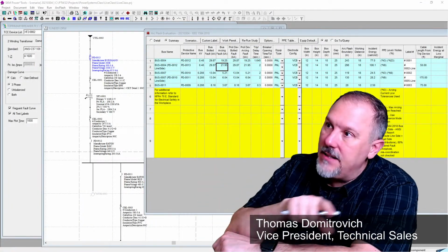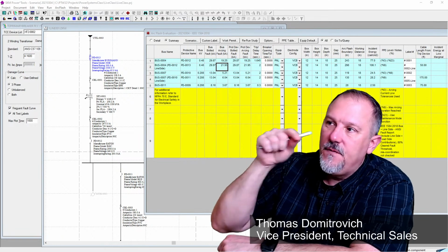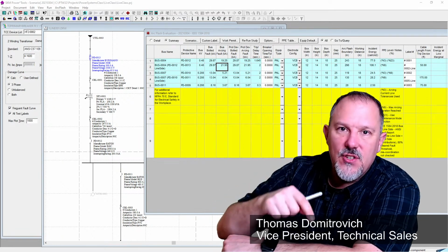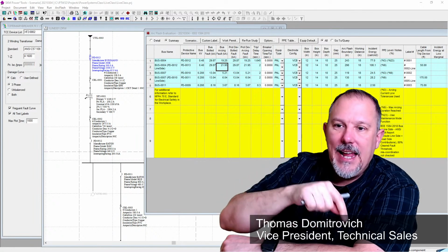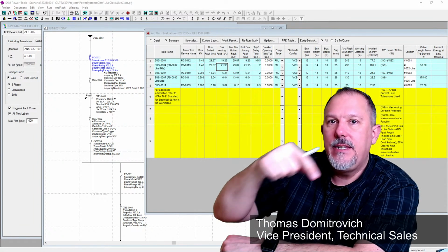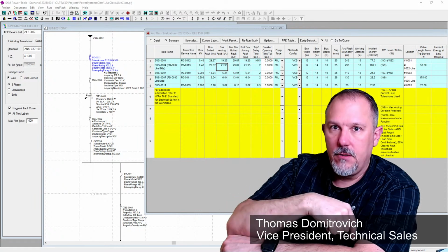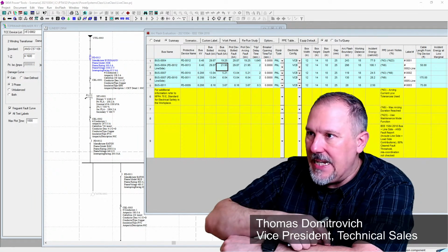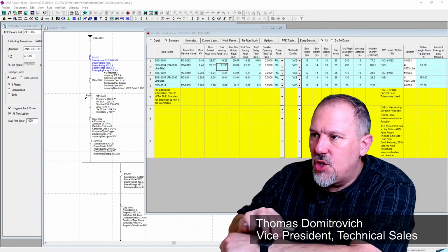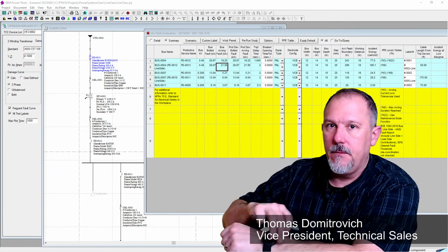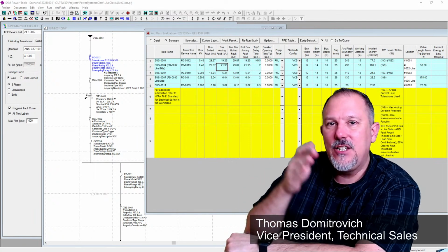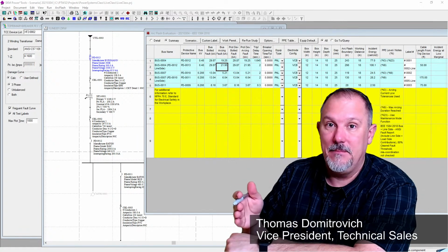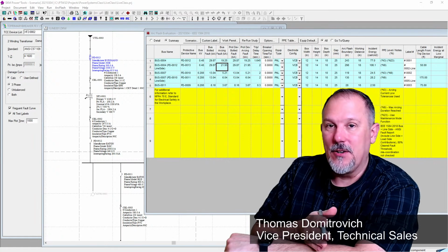Having said all that, for bus 4, we have 29,870 amps. When you're looking at the downstream breaker, this PD12, which is the 2000 amp breaker, that tells me that my higher arcing current is into a faster clearing time than my lower arcing current.